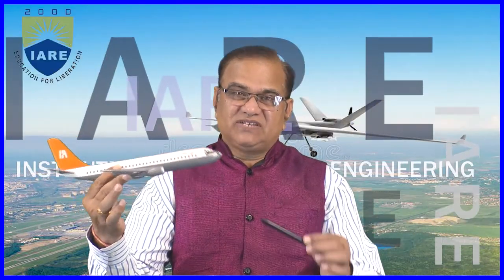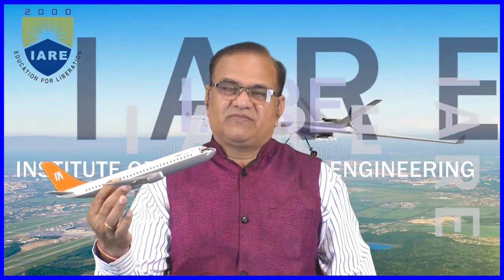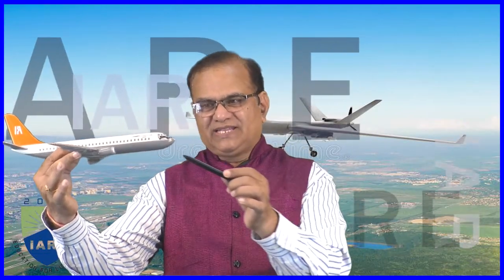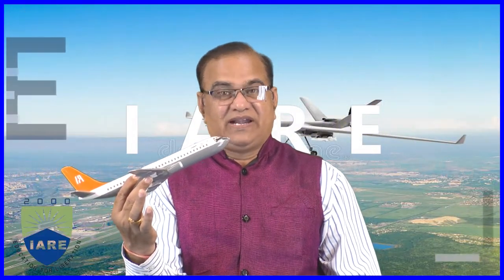And if after disturbance, the aircraft is going away from its equilibrium position, it is called divergence. If an aircraft is diverging from its initial condition, then we can say that the aircraft is statically unstable. And when we disturb it, and after disturbance the aircraft maintains the same condition, like it is going like this, it is disturbed and it is moving like this, then it is neutrally stable. So up to neutral stable, we can accept the aircraft for dynamic stability.